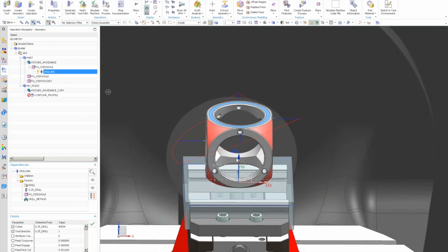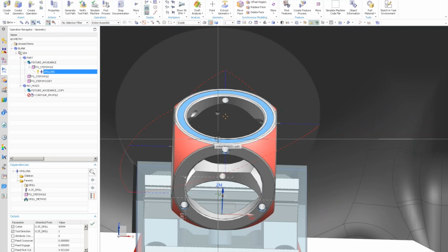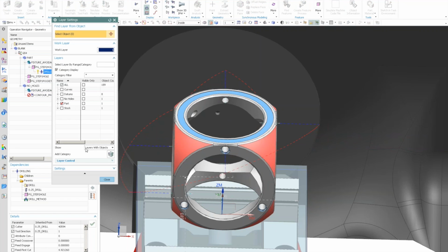All right, so now we want to go in and mill these undercuts, and maybe you don't have time to order a tool. We find that with our 5-axis, without having to have special tools, we can cut many features that we previously couldn't, and we would have had to order custom tooling. We're able to go in and just create a 5-axis toolpath and mill parts, definitely reducing our stock in tooling.